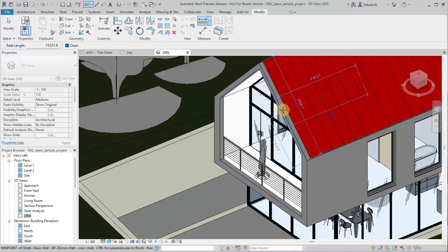After selecting the first point, use the keyboard shortcut SP, Snap Perpendicular, to measure a distance perpendicular to the first point on the plane or line of the second point. Use the measure tool as you work to understand the lengths or distances of elements without placing a dimension element, or when temporary dimensions are not in the positions to give you the information you need.